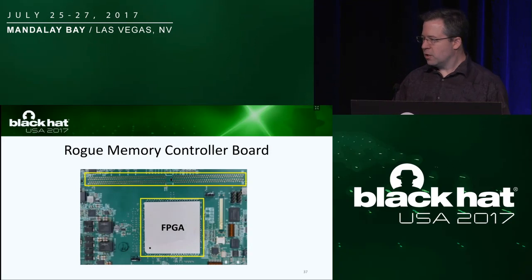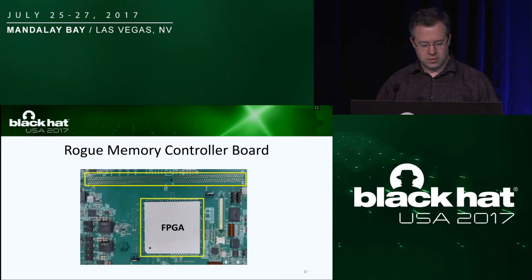So this is a picture of the hardware that I've built. Anna and I worked on this hardware over the last, I'd say, 4 months or so. I've built multiple of these boards. Again, we're using an FPGA, and you can see at the top there's a DDR4 footprint on the PCB. This is where a DDR4 connector can normally be installed. I did build some of these that have a connector. We've been able to put DDR4 modules into those and test that our circuit board works, our FPGA code works, and we're able to read and write. Then we brought this board into the lab and tested that our signals are acting the same way as our victim system.